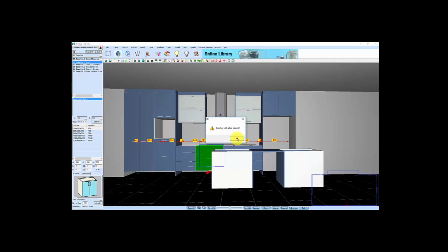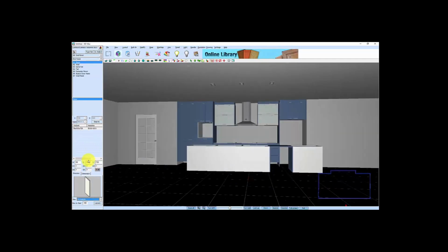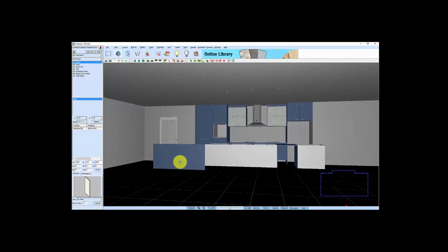So what I want to do now is place a bar back on that cabinet. So we go to base units, end panel, decorative panel, go OK. The width is 1600, is 1921. The depth is 16 and the height is 870. I want to put that on the floor. Let me just press layout. Place that there. Get yourself into a position.